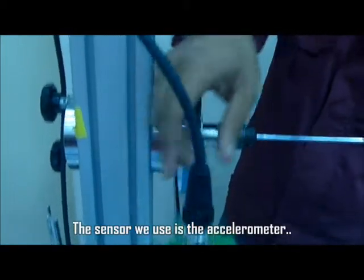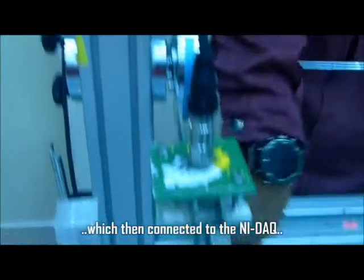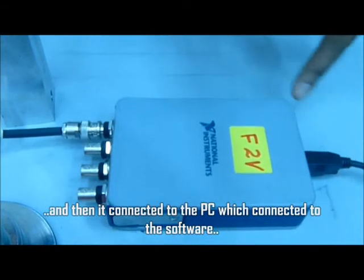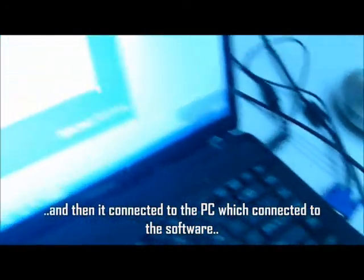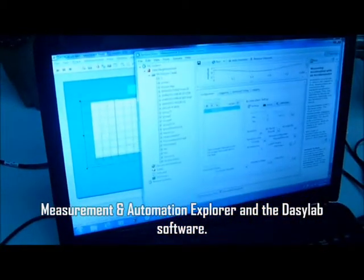The sensor we use is the accelerometer, which is connected to the NIDAQ, National Instruments Data Acquisition, and then it is connected to the PC, which runs the software Measurement and Automation Explorer and the DasyLab software.